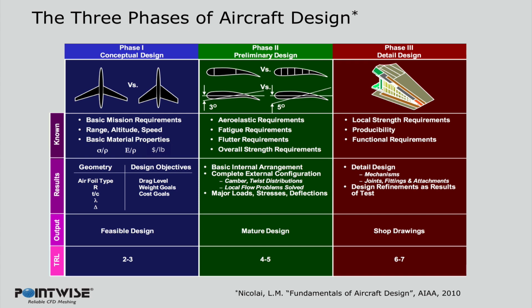Traditional computer-aided design, or CAD, software packages have strengths that are beneficial in the preliminary or detailed design phases, but actually have little benefit or become hindrances during conceptual design. A number of these programs originated in the manufacturing world and are characterized by their high precision, extreme flexibility, and ability to easily represent machining operations. The outer mold line of a typical aircraft is not produced using many of the geometry creation processes available within CAD, and so it takes a highly skilled user to produce aircraft geometries using these tools. As a result, the learning curve for CAD tends to be steep. OpenVSP aims to address these and other conceptual design geometry requirements specifically.